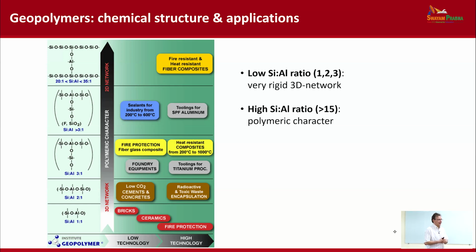Well, the reason is that there is a very strong difference between the structure of a consolidated geopolymer and the structure of, let's say, consolidated Portland cement. In hardened Portland cement, you're familiar with the fact that the solid is held together by secondary bonds, because you form hydrated species in the form of nano-sized viscous crystals, or not real crystals, but viscous, and with a composition similar to that of tobermorite.